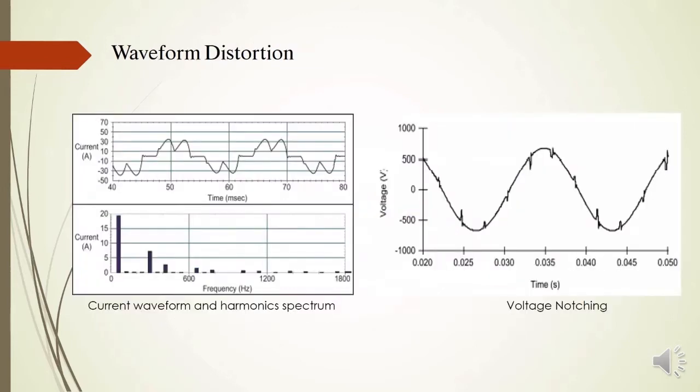The next phenomena is the waveform distortion. Waveform distortion is the steady-state deviation from ideal power frequency. There are 5 types of waveform distortion, which is DC offset, with amplitude of 0 to 0.1%, harmonics with 0 to 20%, interharmonics 0 to 2%, notching, and noise with 0 to 1% of amplitude.